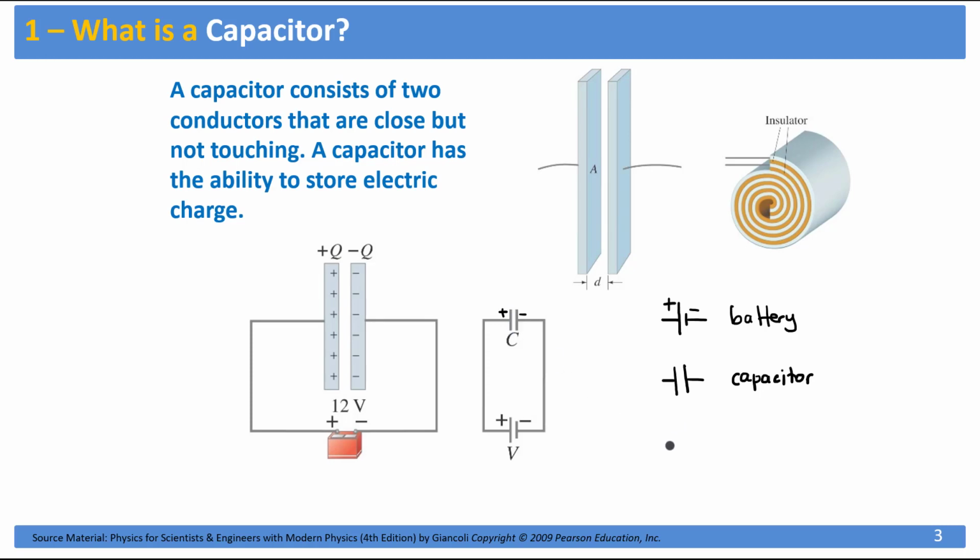Sometimes though, you might come across a circuit diagram where a capacitor is represented like this, which is still a capacitor, but these represent a specific type of capacitor called electrolytic capacitors, and you have to connect these in a specific way to a circuit. It has to be always this terminal that is at a higher potential than this terminal. But apart from the way you connect these capacitors, they behave the same way, so we are not going to discuss this anymore during the remainder of this course. We will just stick with regular capacitors.